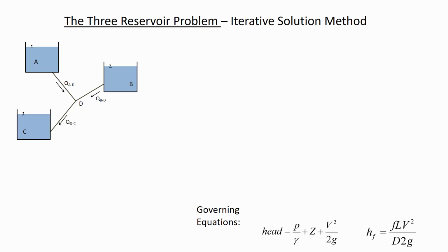Great question. All right, so here's the solution method. There's a step-by-step 1, 2, 3, 4 thing that we have to go through. But first I want to introduce you to the governing equations here. The first thing that we're going to always keep in our minds is the definition of head, which is just another way of measuring energy, but with units of meters or feet.